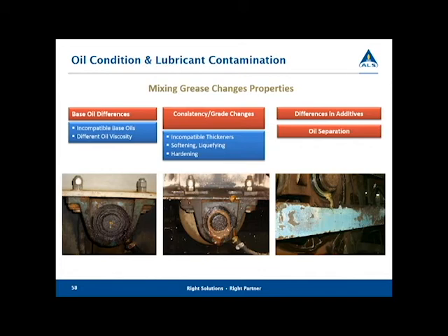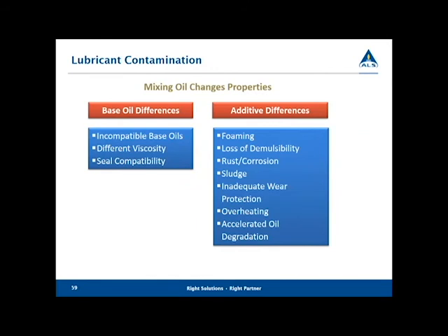I've seen it. These additives compete with each other, be it in oil or in greases. Different companies use different chemistries, and they do compete with each other. It's a really balancing act. And if you mix these things together, oils can separate out. Now, base oil differences: if they're incompatible base oils with different viscosities, they can even have different seal compatibility as well.